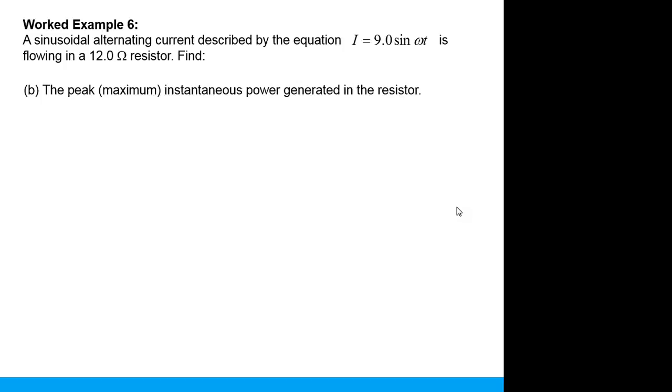Nope. All right. Part B, they ask for the maximum power generated in the resistor. So you have to be very careful. In AC, the power they ask you for could be average power, maximum power, or power at a certain instant in time. So you have to be careful what they're looking at. Here they're asking for maximum. Maximum is easy: I square R, done. I naught square R, sorry. Which means the maximum current squared times R.